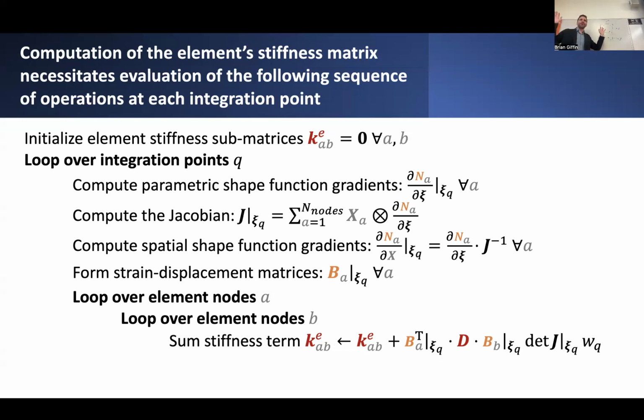But all of that's post-processing. At the end of the day, they never really show you what's going on in the element. They never tell you that all they have to work with are these discrete values of stress or strain located at these discrete points within the elements. And it's important to remember that that's effectively what's happening behind the scenes. Because sometimes in the post-processing, they smear out some of those details and it makes it a little bit difficult to interpret: did I actually exceed some kind of critical stress state?